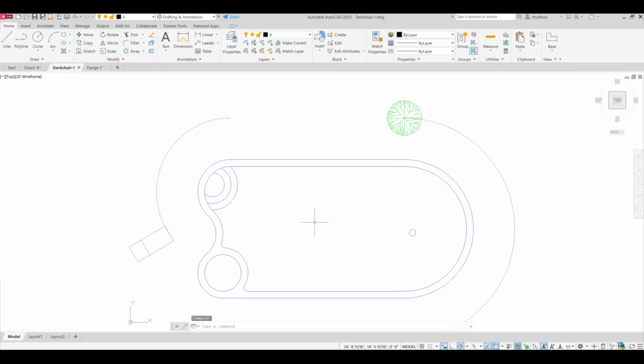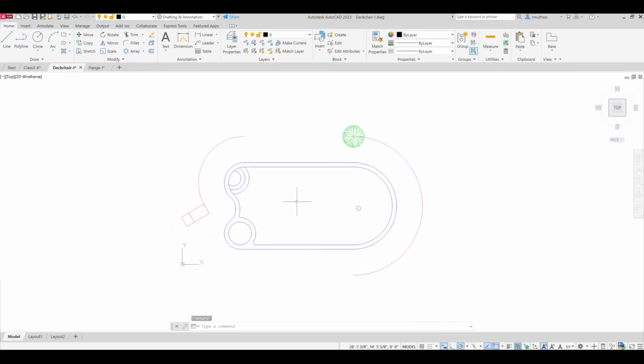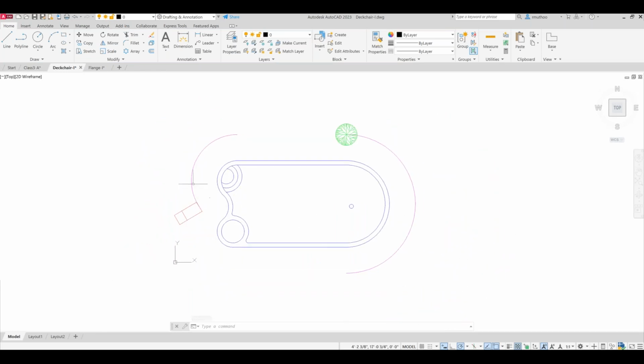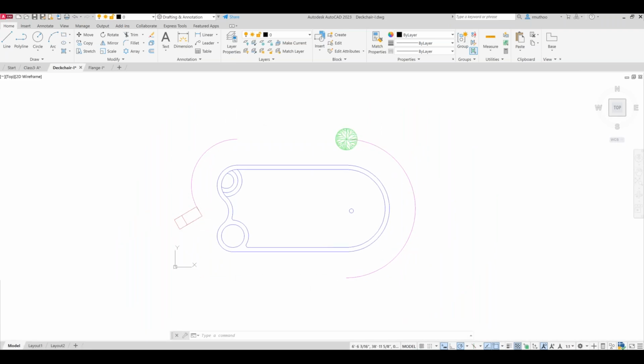For that, again, I have the swimming pool, and I have already created 2 arcs. One is for the trees and the other is for deck chairs. So now if I want to create, again, the array flyout, I will use the path array now. For that, first of all, I select the objects. For example, I want those trees to be going around this arc, this path.